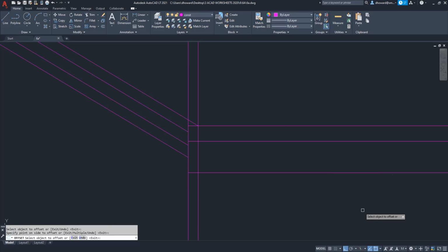And to get our final length on this side, we need the radius of the outer curve, and those radiuses are 3/4 of an inch, so they're all the same. So the offset is 0.75. There it is. So that's the final length of this guy. Okay, so that takes care of the vertical piece right there.